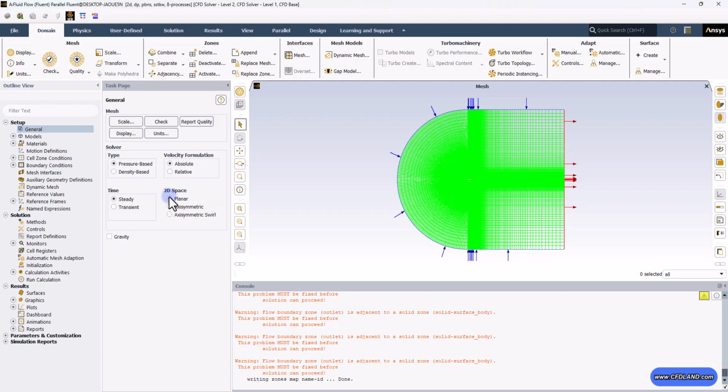and we are simulating the transient flow. And in general, in any case that we can neglect the compressibility effects, we tend to use the pressure-based solver. So in aerodynamics, if the Mach number is below 0.3, the air is considered incompressible. The density doesn't change much. And it means we can use the pressure-based solver type. In simple words, we are excluding all the derivatives of density from our Navier-Stokes equation.